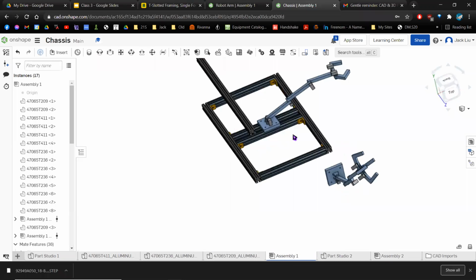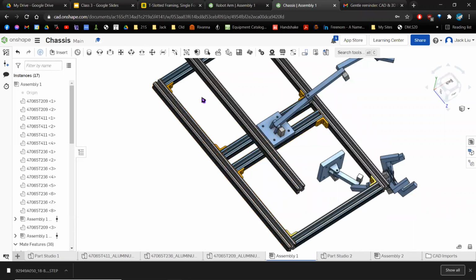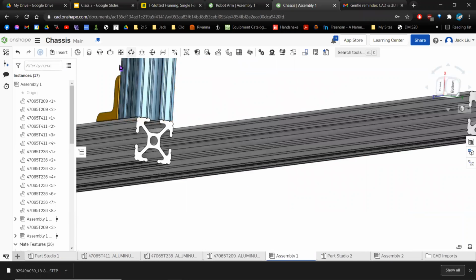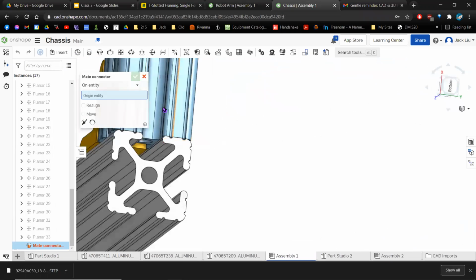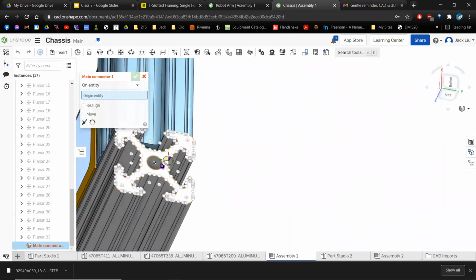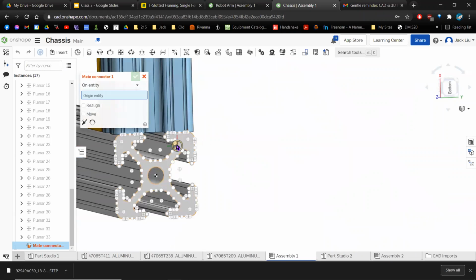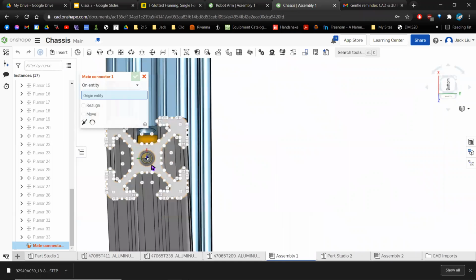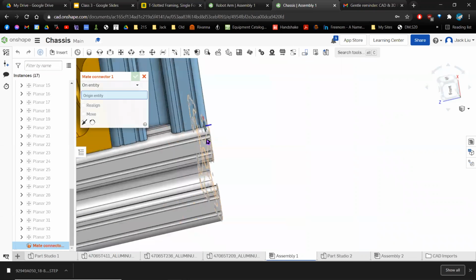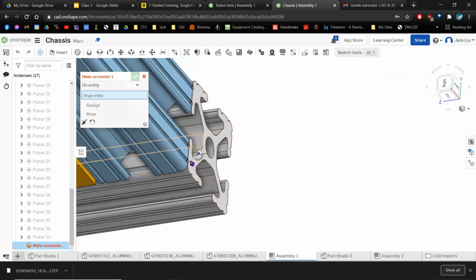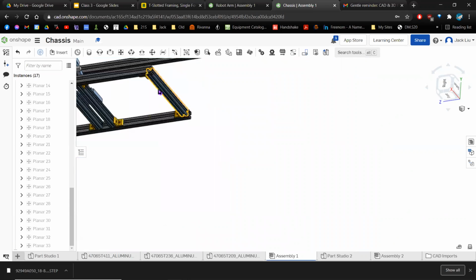and use them in your assembly instead. It will be slightly more complicated because if I go to my fasten mate, for example, it's gonna start complaining. There's all these different points that you can attach to. And that's just because the real 80-20 beam is a lot more complex than just a square or a rectangle. And so you have to be more careful about where you're attaching what to. Right? But overall, it's the same process. You just match up what points connect to each other and you rotate it around if necessary. And you form some sort of frame.